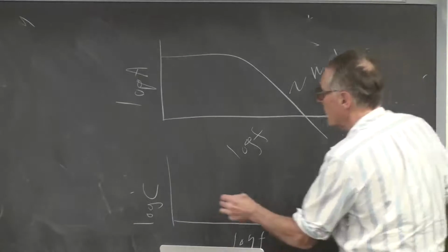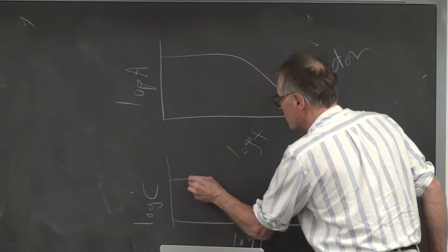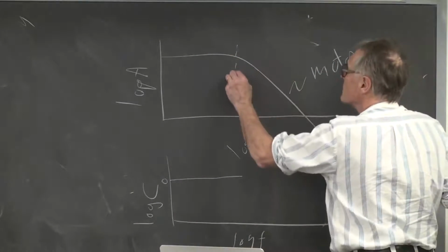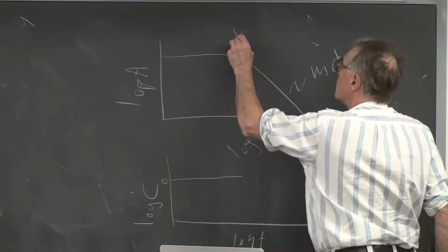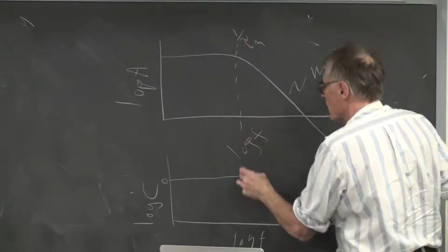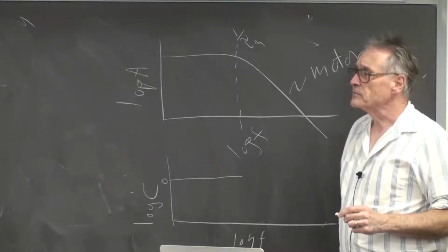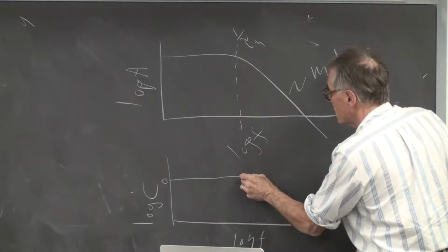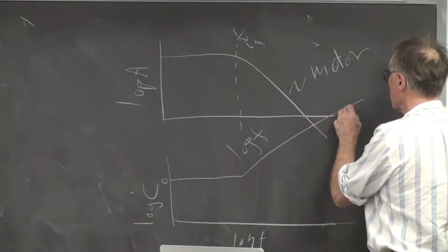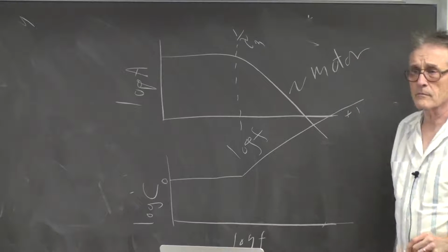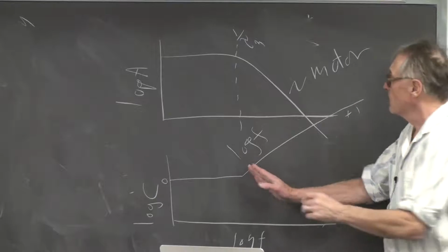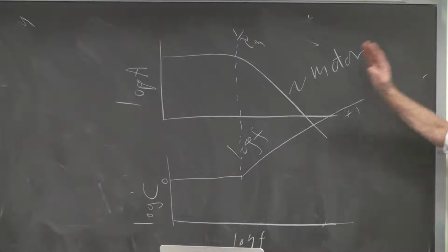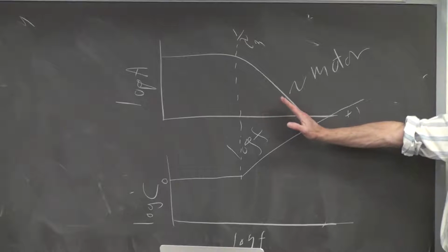What happens if we don't add any phase shift at low amplitude? So this is 0 phase shift, but right about where tau m cuts in, 1 over tau m, we start adding some phase shift. Let's make a differentiator with a slope of +1, whose differentiator cuts in at about the frequency that the motor starts to cut out.